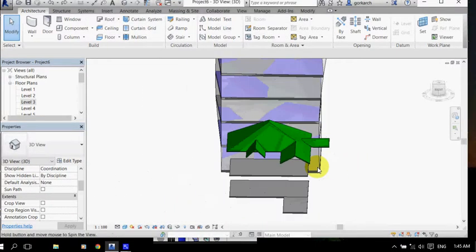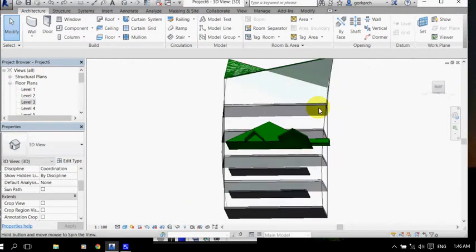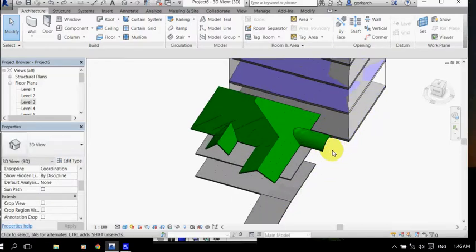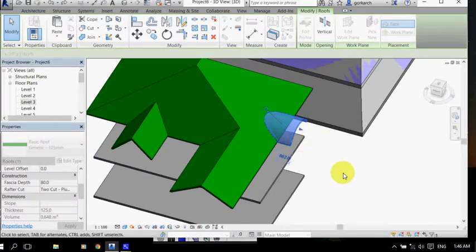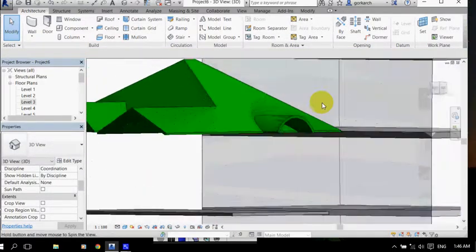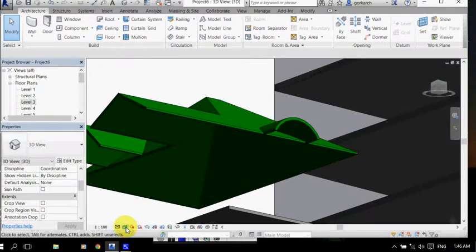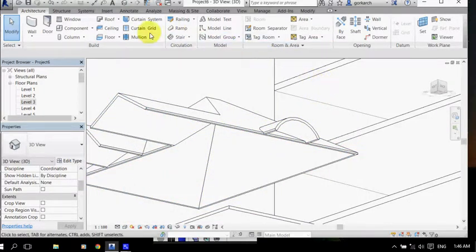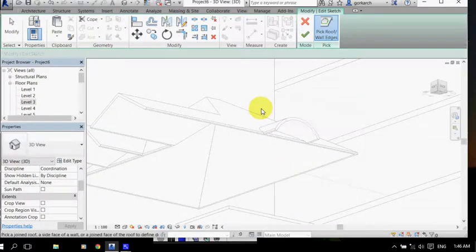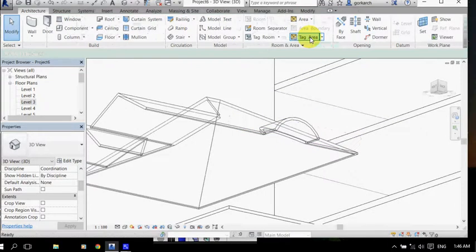Now let's have a look if we can have some proper dormer openings. So I'm going to stretch this element slightly back. Have a look from below. For this operation I suggest you switch to hidden line, and under the Architecture tab select dormer opening, select the main roof from which you're cutting, then select a smaller roof, select the edge and finish.